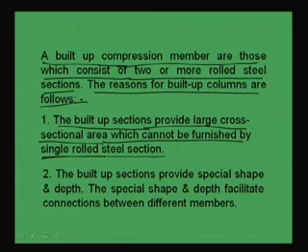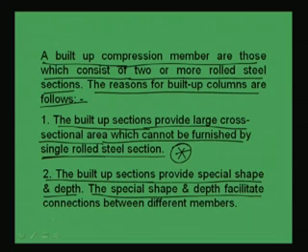So this is the main, general, simple reason for which we generally make them, but other reasons are there which I have discussed. Again I am writing here. Another is that built up sections provide special shape and depth. The special shape and depth facilitate connections between different members. Because of different shapes and depths, we can make the connections at our own choice.